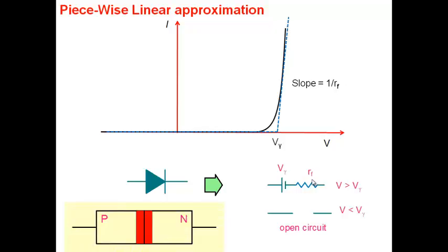Now, there's another misconception associated with it. As I said, the first misconception is that the cut-in voltage refers to the voltage across the depletion region. It's like the built-in voltage. And the misconception is that this R that you see here in series is an R which is inside these regions here. Now, it's true that when you take an N-type semiconductor and a P-type semiconductor, N-type has a certain resistance, P-type has a certain resistance. But those resistances are not what we found here.